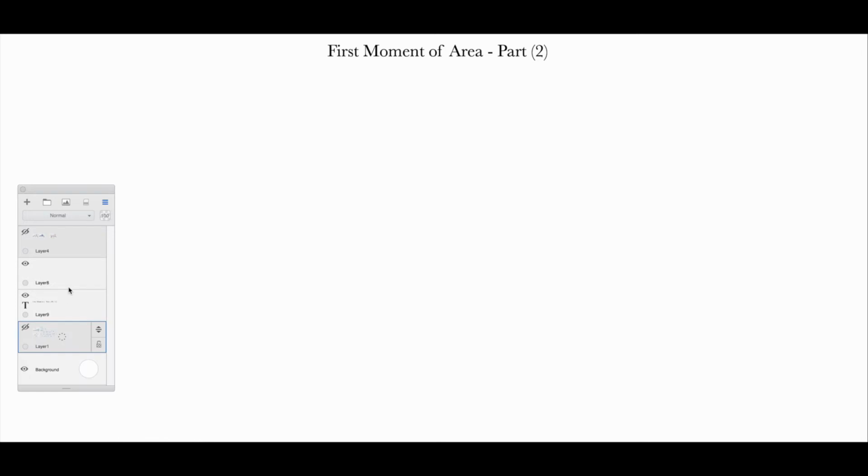To find the centroid, we need to divide the first moment of area that we found, number 4, by the area. So x bar equals the first moment of area divided by the area for the whole thing, which is a squared b divided by 4, all over the area ab over 3. So this will give me 3a over 4. So this is the centroid in the x direction.